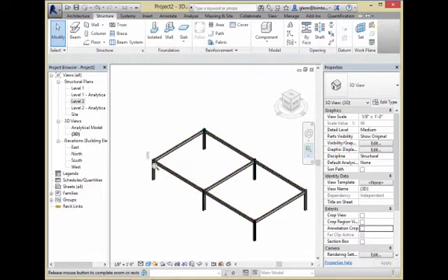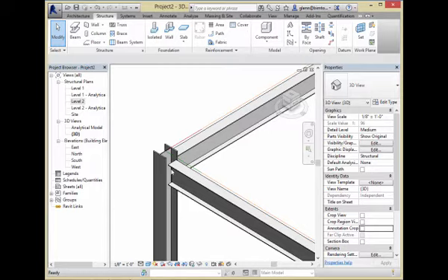Okay, so in terms of true construction technology, that's a little bit closer. I tend to have those a little bit lower. Don't worry about the fact you don't see any haunches or braces or any welded connections. We'll add those in again later. Analytically, this is going to work. These lines that you see in the funny colors are called analytical lines. Those are actually the structural model layered right on top of the physical model. So those colored lines are what's going to be important and go over to the analysis software.